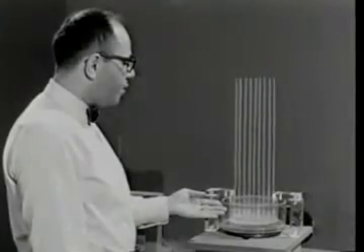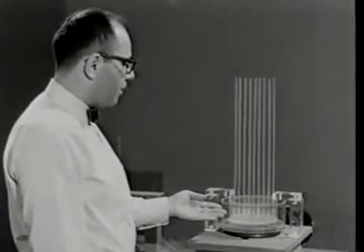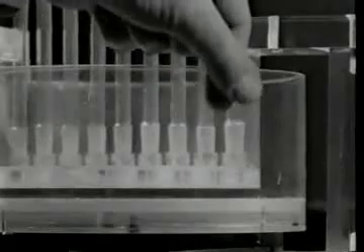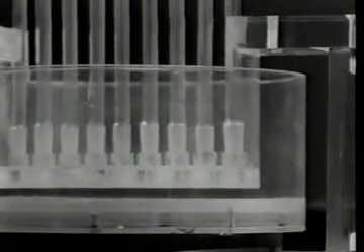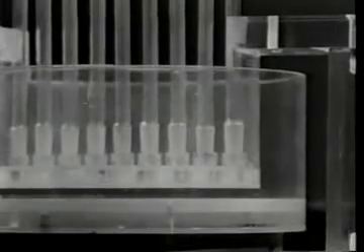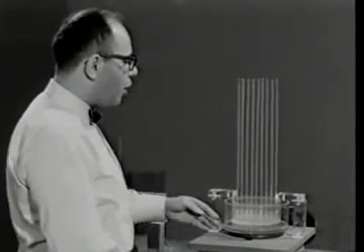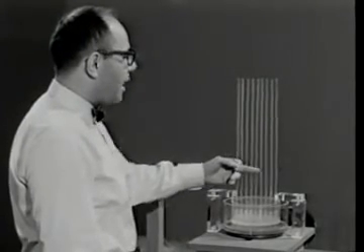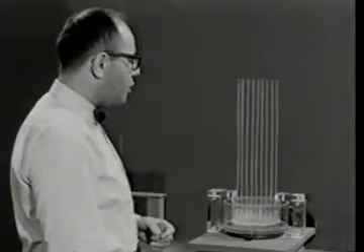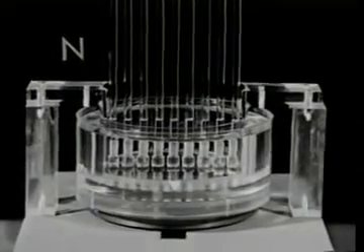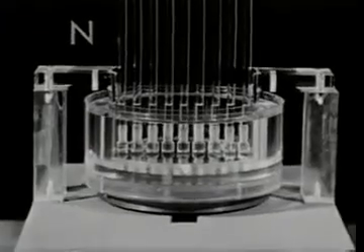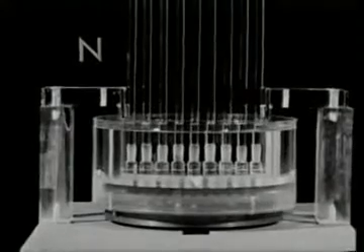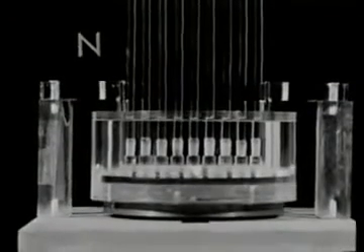Here is another apparatus where we can observe a related phenomenon. This time, the material is sheared between two parallel discs, one of which can rotate, while the other is stationary. The distribution of stress normal to the stationary disc will be shown by the level of the fluid in these glass tubes. Of course, this level will be uniform in the tubes if there is no rotation. Remember, this time we are not concerned with the flow in the annulus between the vertical walls, but with the shear flow in the narrow space between the flat plates.